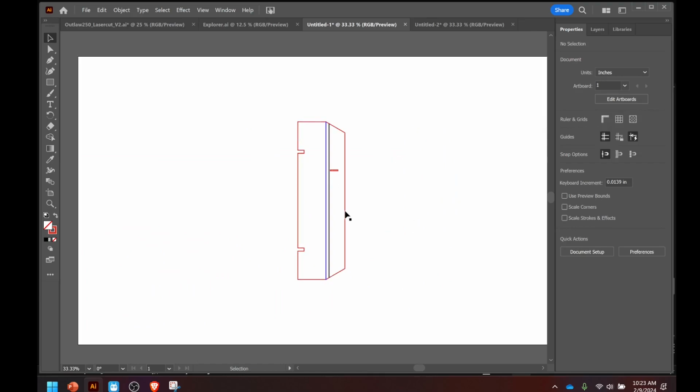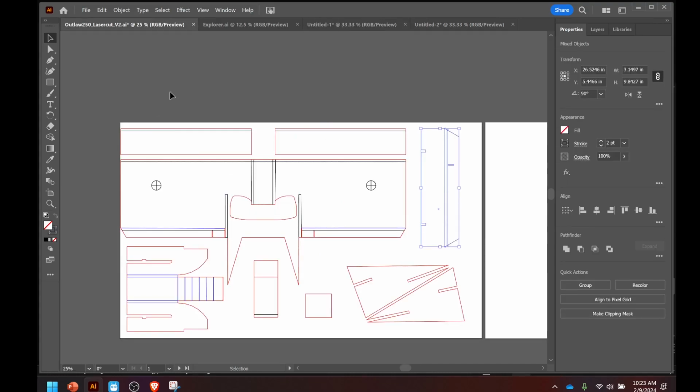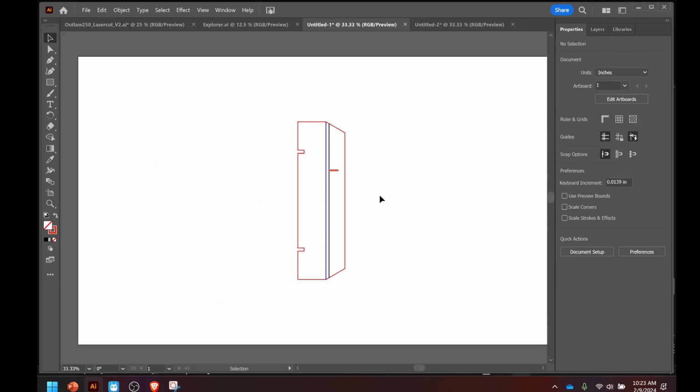And so here's that elevator here. It's pasted in already. And now you can modify the elevator. Now when I had this file here, I changed all the lines. I made them all a bit thicker so we could see them easier. So remember, you always need to make the lines thinner before you go to the laser cutter for it to work right. But let's say like we had in class, we have this elevator here.